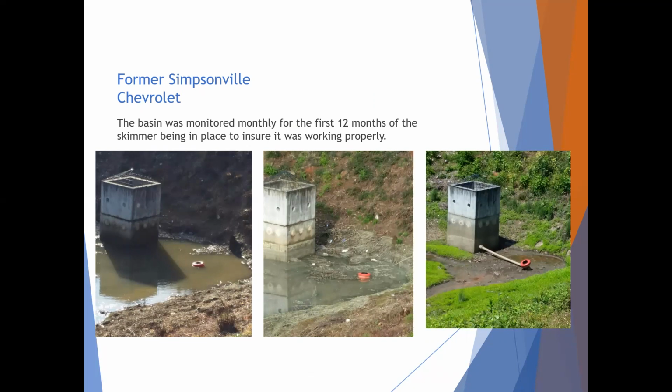So we got with the county and redesigned the basin. And when we did that, we closed up these orifices and moved some up higher. The pond actually had some extra volume available, but the county wanted a 2-inch orifice back in the bottom. And the owner was very concerned, obviously, about how hard that would be to maintain. It's hard to tell from this picture, but that's about an 8 to 10 feet height there. And remember, there's 6 feet down below.